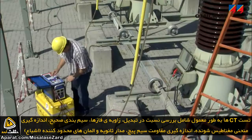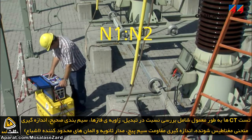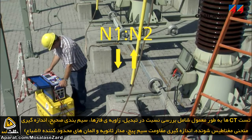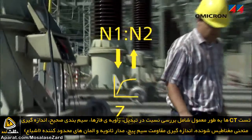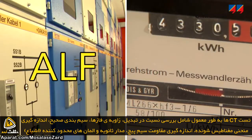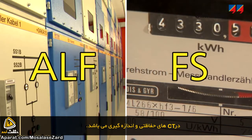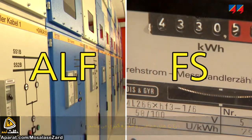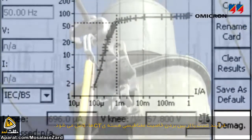Thus, testing of CTs normally includes verifying the ratio and phase displacement, testing the polarity, measuring the magnetization curve and knee point, measuring the winding resistance and secondary burden, and calculating the accuracy limiting factor for protection CTs, or the instrument security factor for metering CTs. It also includes the demagnetization of the CT after testing.